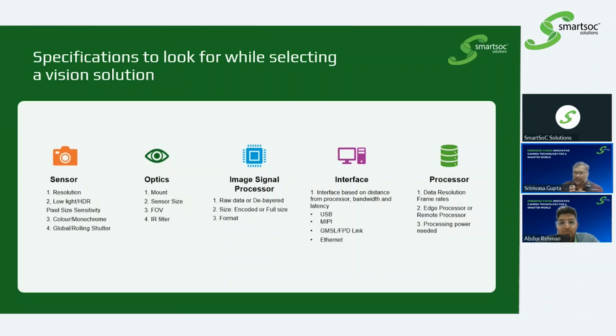Okay, generally when we pick sensor, lenses and ISP altogether, then we need to tune according to our need. So what color quality is required? Are we capturing color properly? That means if your object is a banana, yellow, that should also reflect as yellow, correct? So these parameters need to be set. So the tuning part is required: correcting or setting proper values for all these parameters.